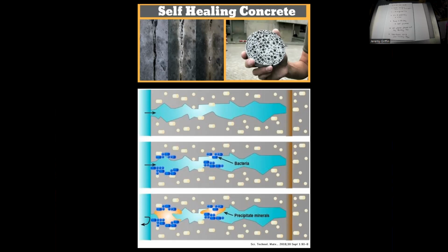So things are going to crack and fall apart. So your cracks start to form. You have to go make repairs. But if you embed this particular bacteria and it goes dormant, right? And you also embed some yeast that it can eat as a food source. Then when a crack forms, it gets exposed to the oxygen. It wakes up from its dormant state, eats the yeast, excretes the calcium carbonate, and boom, self-seals. So it's all good again.